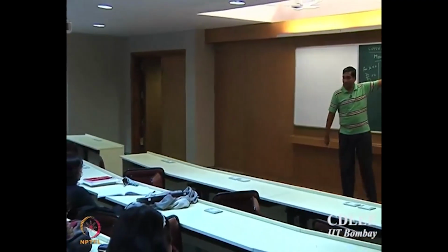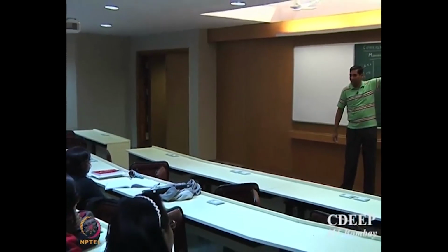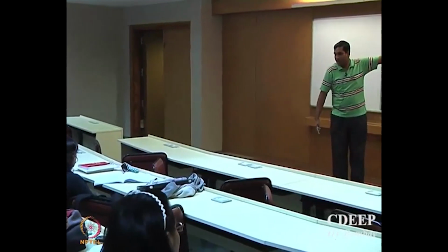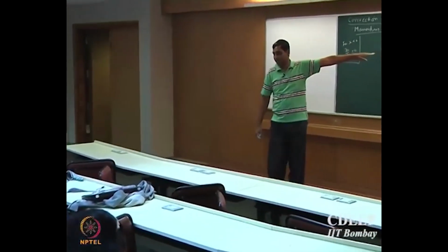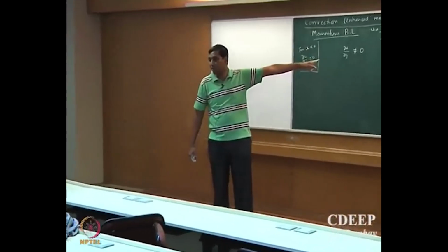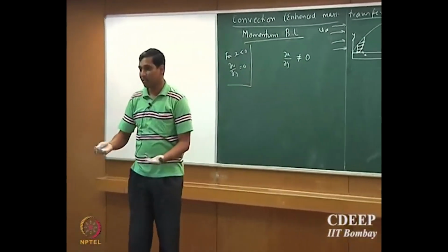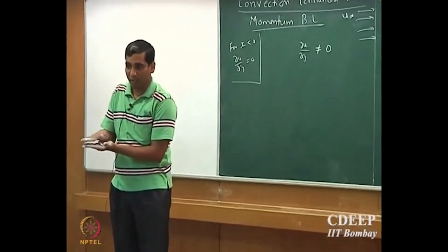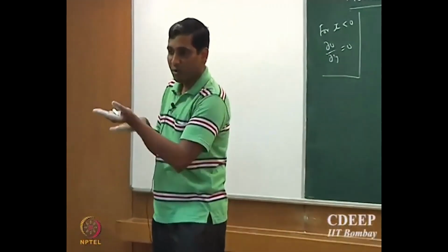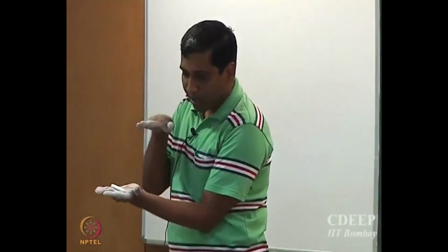That is true, it has a viscous shear. We are going to talk about shear stress very soon, but note that it has viscous effects. Now because of viscous effects, you will see that the gradient is going to come in both directions, and in fact the retardation, why does it retard? Because there is a definite viscosity, and so when there is one fluid particle which is at rest, the other fluid particle is trying to flow at a certain velocity, but it is going to offer a retardation because of the viscosity, right.